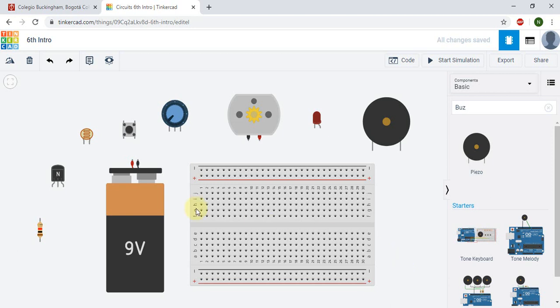In order to create wires, you simply have to select the lead or the joint that you need and click once and join it. I'm gonna show you with the battery how it works. So I'm gonna join the negative, click once, I move, then I click twice here in order to create like a turn, then I click here, and finally I'm gonna connect it here.